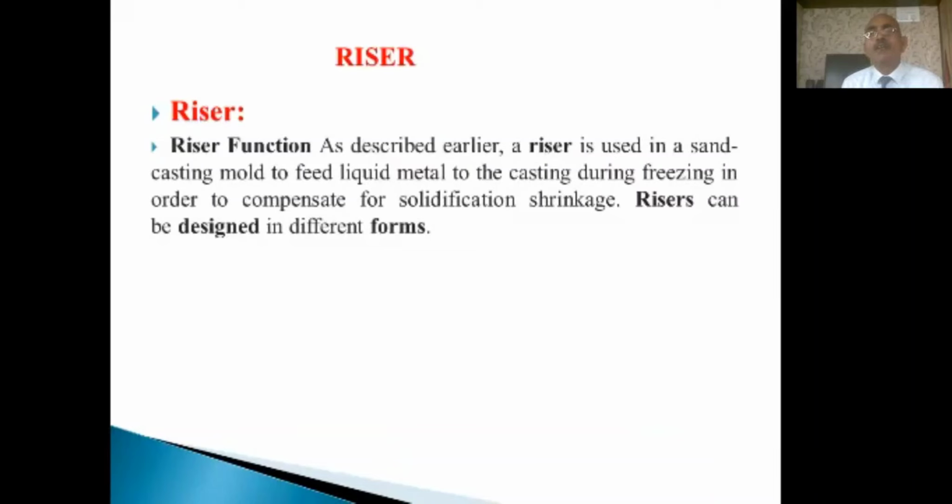What is the purpose of the riser? Riser is used in the sand casting to feed the liquid metal during the solidification or freezing process of the metal. Whatever amount of material shrinks, that much amount of metal is given by the riser.